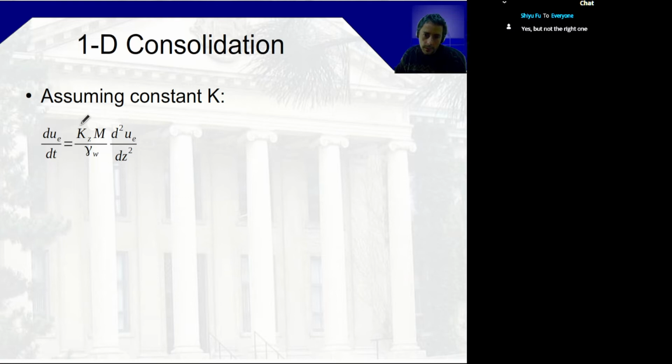What it comes down to is the mechanical strain, so the modulus of the soil, how it compresses, and its hydraulic conductivity at its initial void ratio, which is also a function of the void ratio and water content. That's basically what CV is. CV is basically hydraulic conductivity, the vertical one, so that's why it's Z, times the modulus, over gamma water.